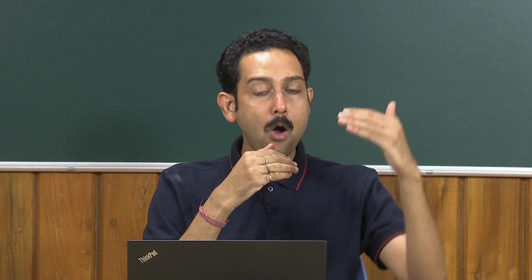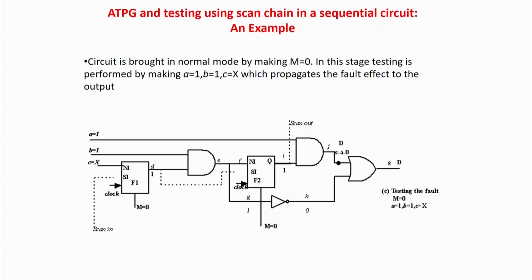So one challenge is, how can you bring down the ATPG, or the number of test patterns, and still have minimum compromise in coverage. Secondly, about the scan chain. If you make a very long scan chain, the time to insert the test pattern in the shift register will be very, very high. So what can I do?